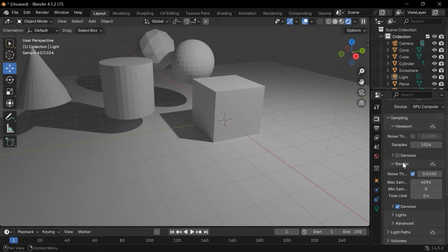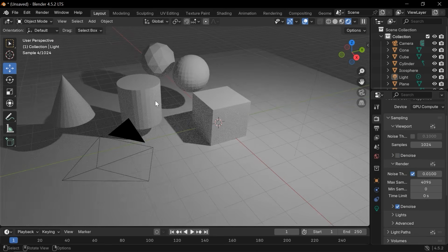Denoiser should be activated in the final render. It is better, but here we need to deactivate it because it will make the process very slower, and we don't want it for the viewport, because actually a preview of the final render is sufficient for the viewport rendering. For the final render, the max sample is much larger than this value. We can specify a value based on our needs. Mostly I use 500 or 600 for my personal renders and use denoiser for the final render.